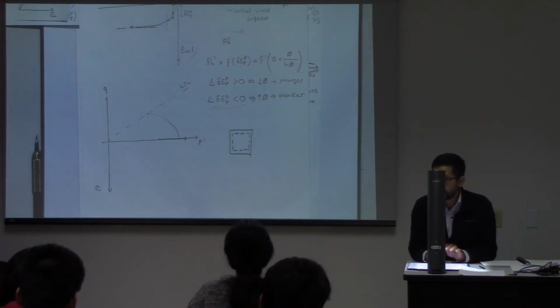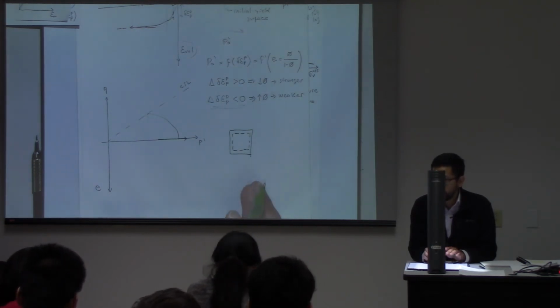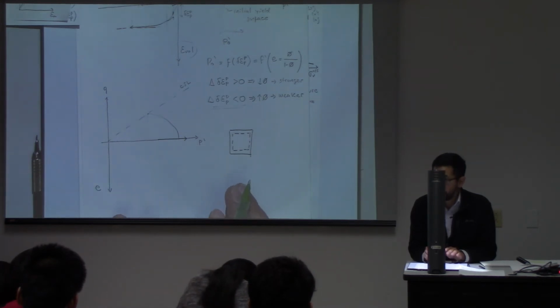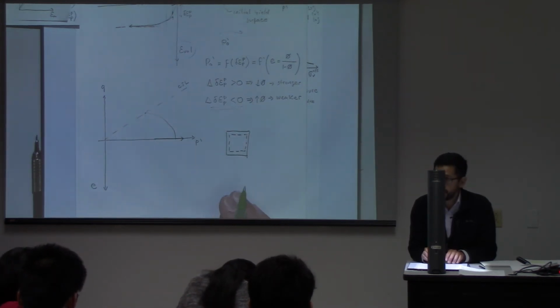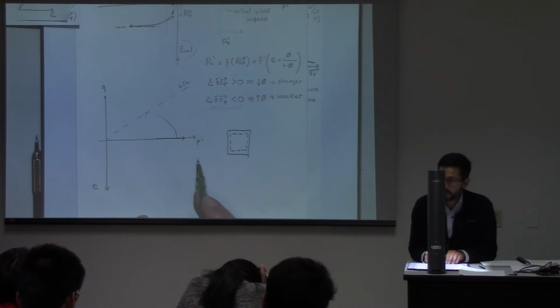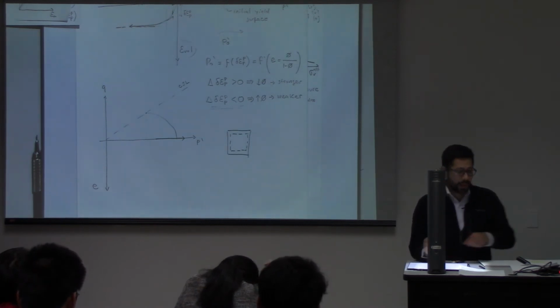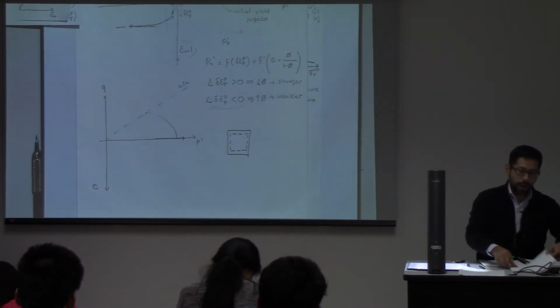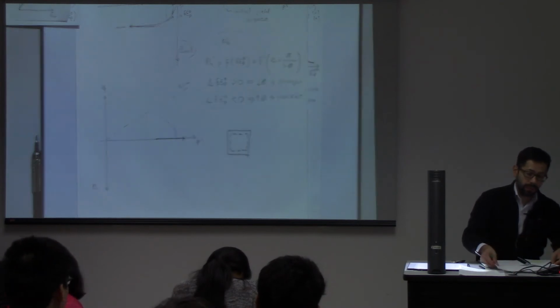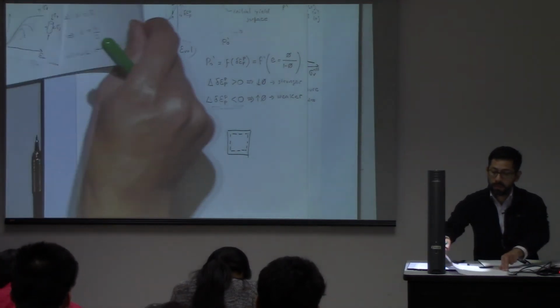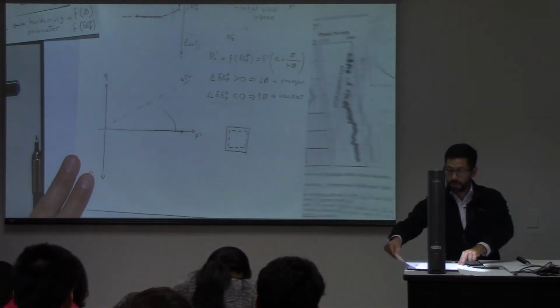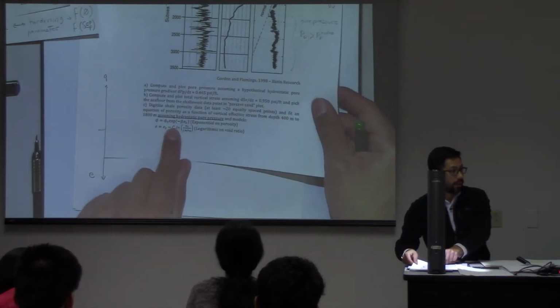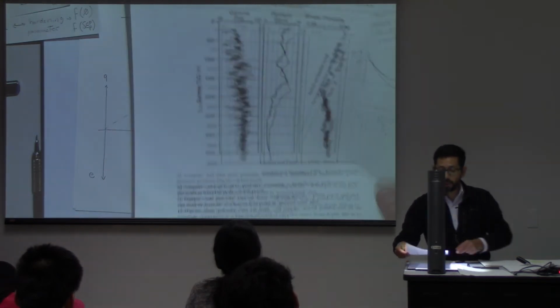These materials are not linear elastic. They can be elastic sometimes, but they are nonlinear. And that relationship, as I shared with you in the problem, is either logarithmic or exponential.